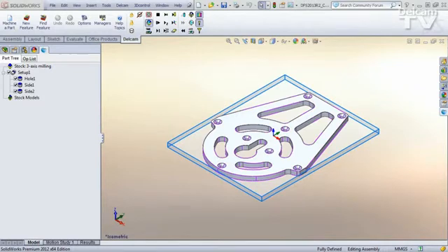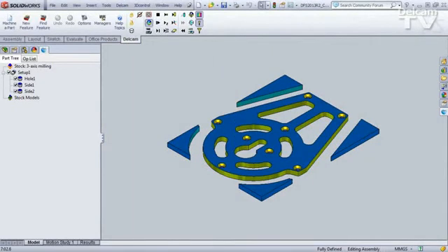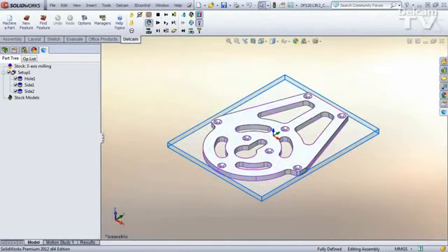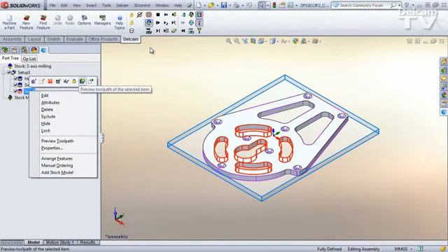So here's a part already programmed, very simple. We're in a 3D simulation, 3 features, and I'll show you these preview enhancements. If you recall now, preview was introduced in 2013 R1, and it gives you the chance to run a centerline simulation for a specific setup or feature or operation. So I'll use a feature in this case, and to get to preview, remember you can right or left click to get either your context menu or your right mouse button menu.